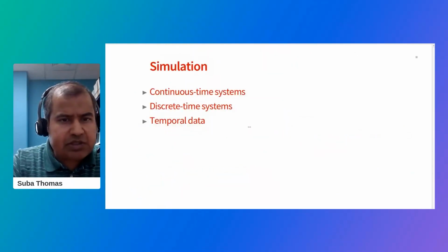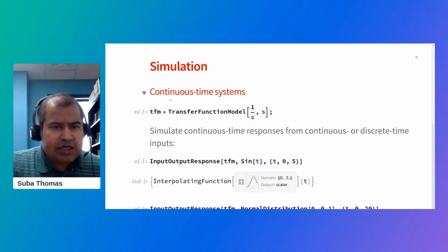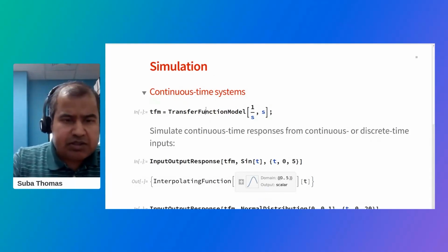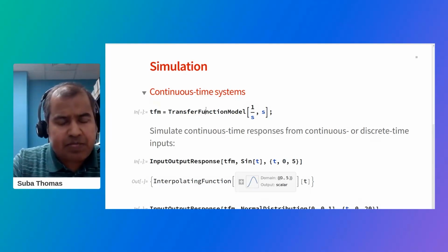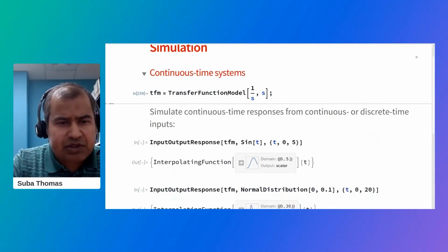And I can see the actual and reference signals. Okay, so some of the things I want to point out from the previous slide: when we did that simulation, we had a sampled data system with mixed discrete and continuous time systems. And we just gave it a normal distribution. Typically when we have a continuous time system, we'll give a continuous time signal.